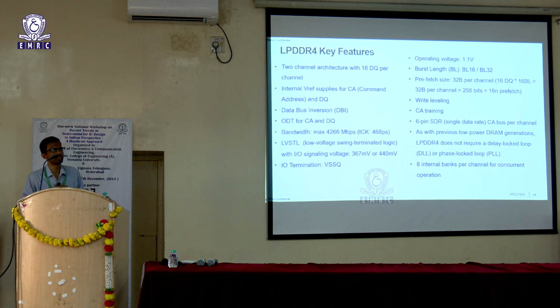Data bus inversion, I will talk about in a subsequent slide what it actually means. ODT is on die termination. We talked about high speed interfaces here running up to gigabits of transfer speeds. When we are doing data transfers at that high rate, you need to have proper terminations, and ODT is used for that. And LVSTL is low voltage swing terminated logic. So, instead of open drain logic, we have something called low voltage swing terminated logic. I will talk about this also in a subsequent slide.